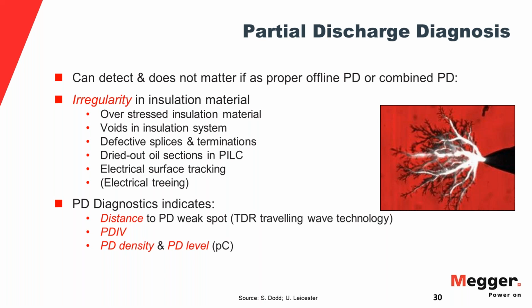All of these things will cause partial discharge and electrical treeing at one point. At one point, water treeing will cause electrical treeing, even though those electrical trees are of a very different magnitude than real PD. So typically, it's very difficult, borderline impossible, to really catch those.